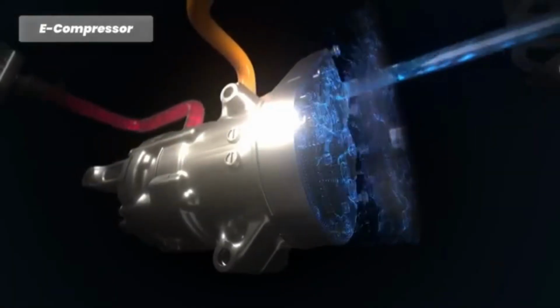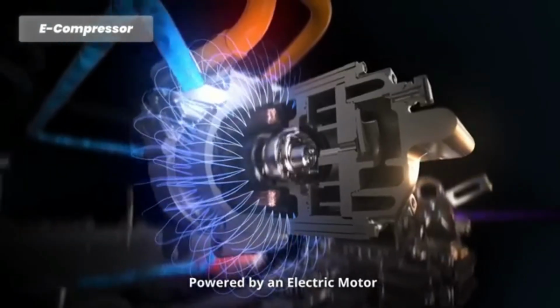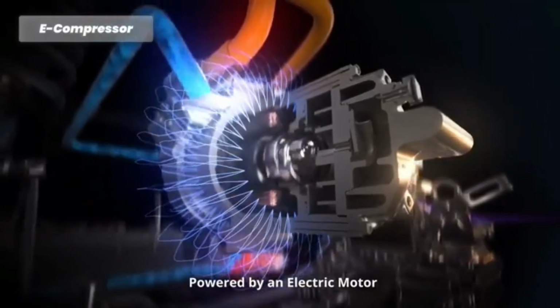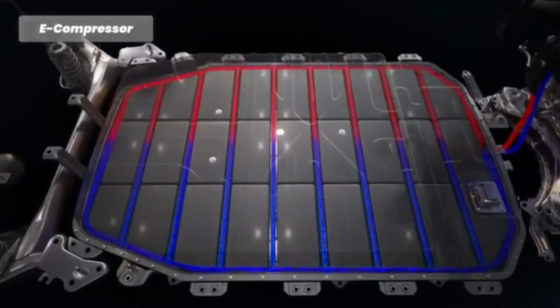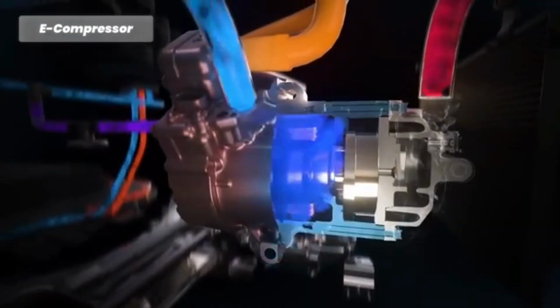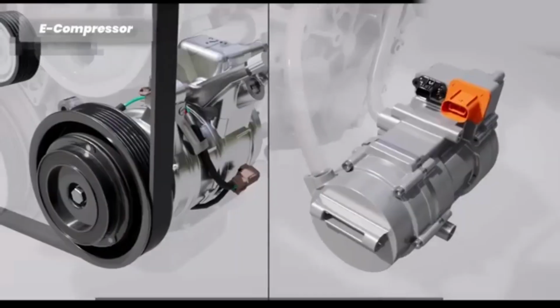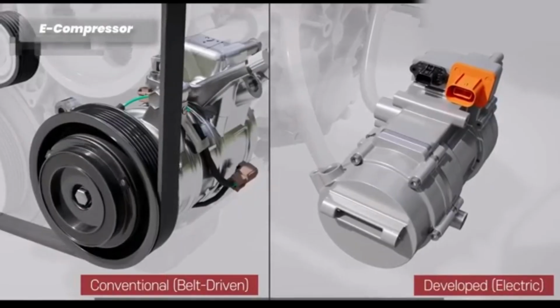In EVs, the AC compressor is powered by an electric motor. This motor is driven by the vehicle's high-voltage battery system. Electric compressors have fewer moving parts and do not rely on belts, which can reduce maintenance needs and improve reliability. In summary, while both IC and EV AC compressors achieve the same goal of cooling the vehicle's interior,